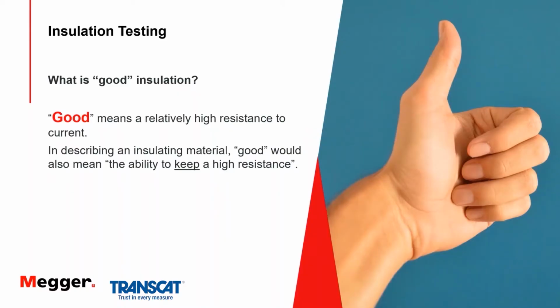So then, a seemingly simple question, but one that is really rather complex as we'll see as we go along: what actually is good insulation? The answer to that is not at all straightforward. It's pretty varied, and we'll cover it this morning. But fundamentally, good insulation is the value that you need for your equipment to be safe and operate properly. And also, you want to be able to keep a good reading, because insulation will deteriorate over time. That's part of the reason that you test it, and we'll come back to that again and again.